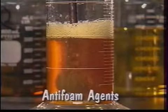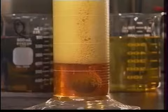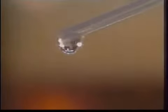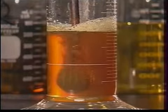Anti-foam agents eliminate lubricant foaming caused when the churning action of mechanical parts creates bubbles by mixing the oil with air. Excessive foaming reduces lubricant effectiveness by disturbing the hydrodynamic film between meshing parts. Foam inhibitors prevent this problem by decreasing the surface tension of the lubricant and allowing the air to escape.